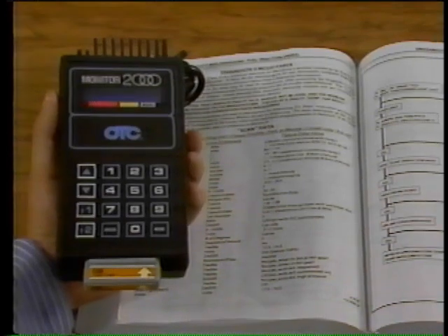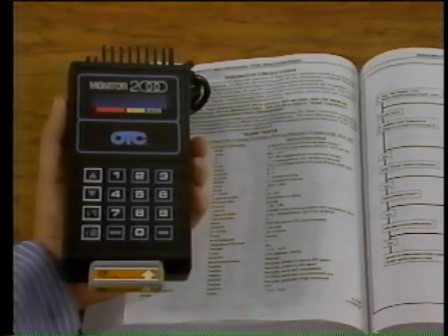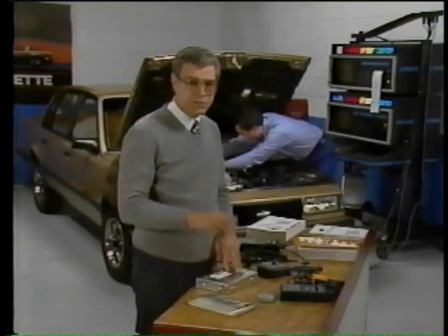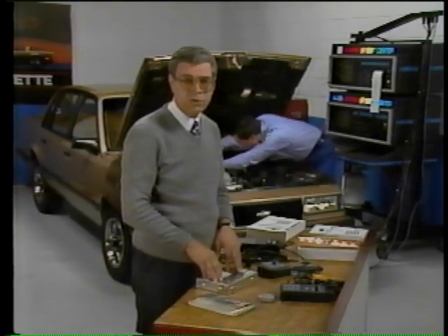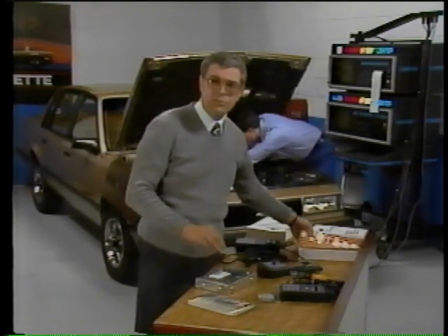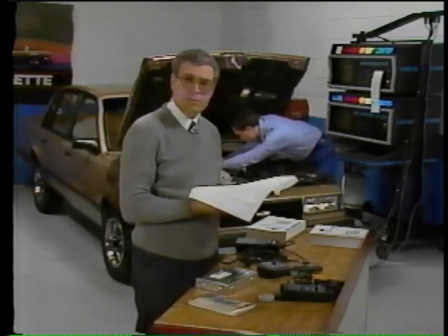This information is meant to be used after completing a diagnostic circuit check and not finding any trouble codes. The specifications listed are used in conjunction with the scan tool readout. They give you a baseline with which to compare the status of various system components. If the readout of a particular component isn't within these specifications, chances are something is wrong with it and requires further checking or replacement.